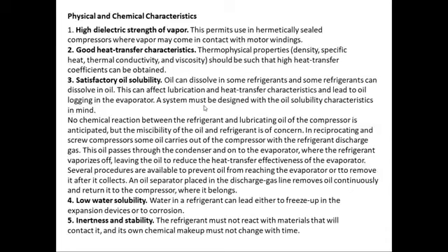Because these lubricating oils normally are not as thermally conductive as the refrigerant itself, it will act as an insulator and reduce the refrigerating capacity of your system. So that's the other reason. One more apparatus that we use is the oil separator. After the compressor, there is normally an oil separator installed for the same purpose.